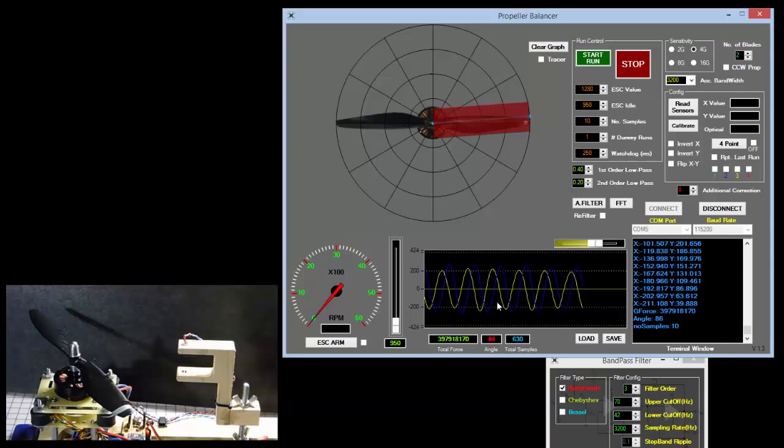So you can really begin to see the effects of a well-designed DSP filter. And then again, the only way you can play with this is by choosing different filter types. It could be certain imbalances with your rig. Some filters are more linear, others are better at maintaining constant phase, others are better at having a sharper cutoff, like for example the Butterworth filter here.